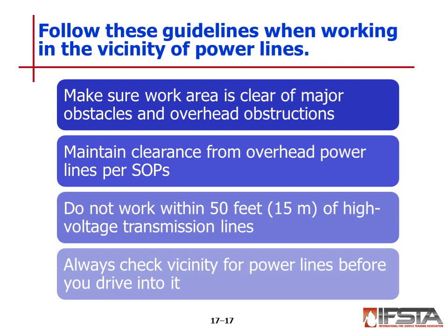Some guidelines when working in the vicinity of power lines. Make sure the work area is clear of major obstacles and overhead obstructions. Maintain clearance from all overhead power lines per your standard operating procedures. Do not work within 50 feet of high voltage transmission lines.